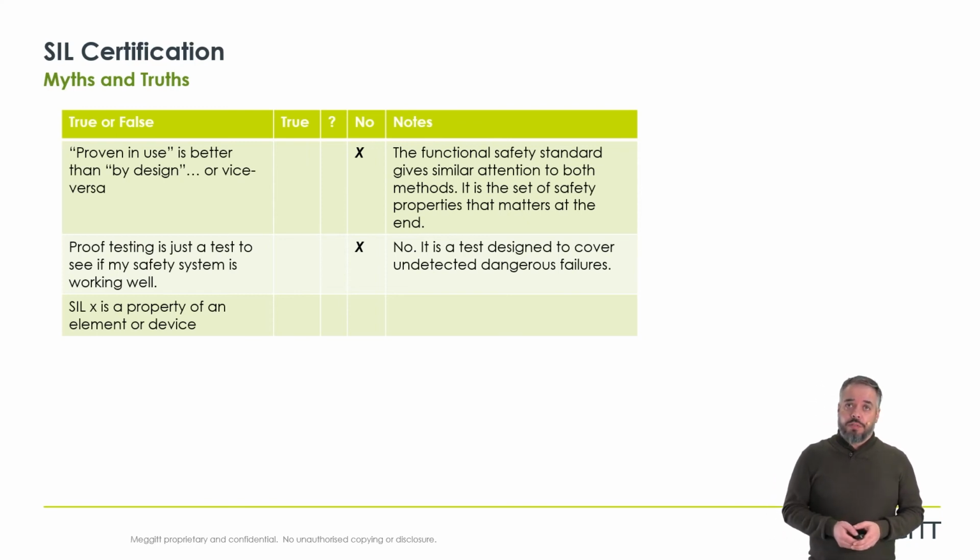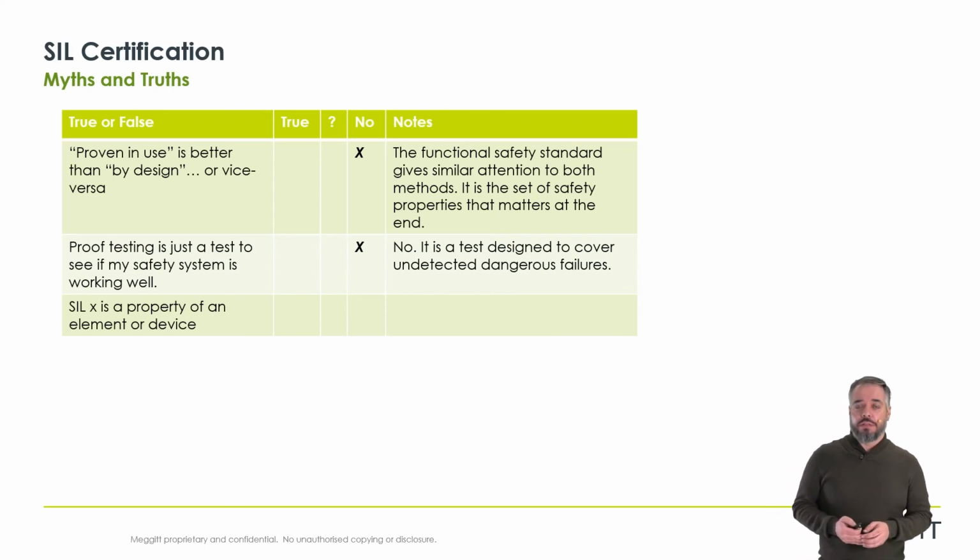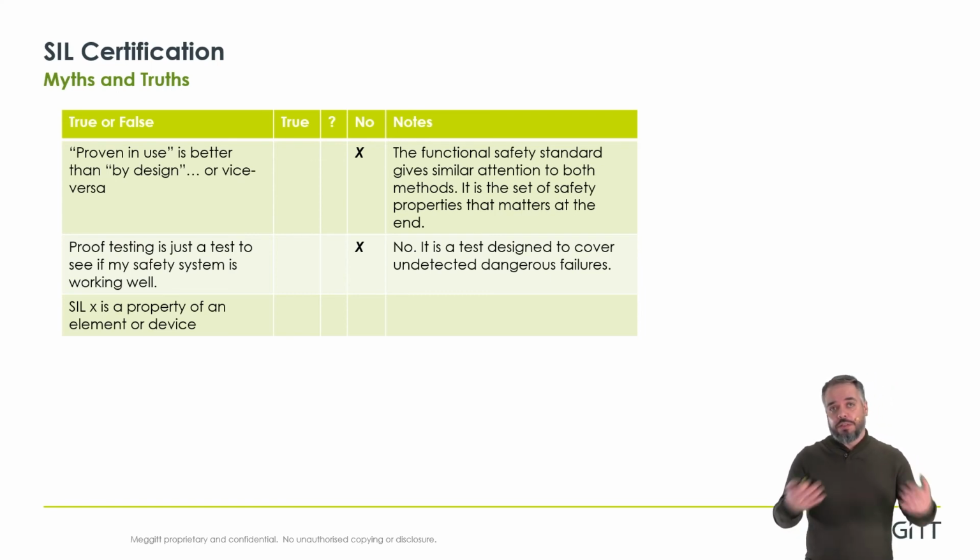Is SIL a property of an element or a device? The correct interpretation of SIL is the capability to implement safety functions up to a certain SIL level. So it's not a property of the element by itself. It's this capability to be used in safety, to integrate it in safety instrumented systems to implement safety functions.